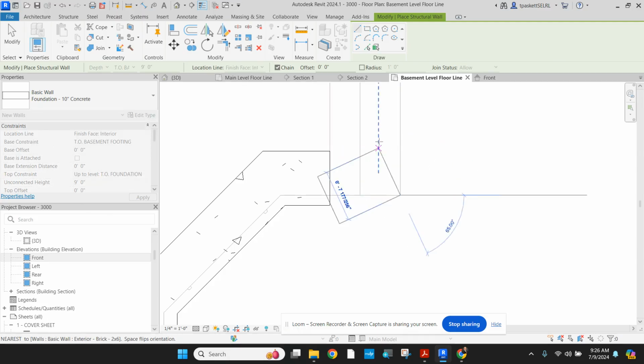And now if you look, when I'm drawing, the brick is going to overhang the foundation just a little bit. That is super important. Your stone and your brick, when there's rain or sprinklers on there, you want there to be an overhang for water to drip off and not soak up underneath into the foundation. Because of the way that's set, we can't really do the same type of condition we have with siding. So that overhang is really important. And that's what you're creating, that little gap between the two.